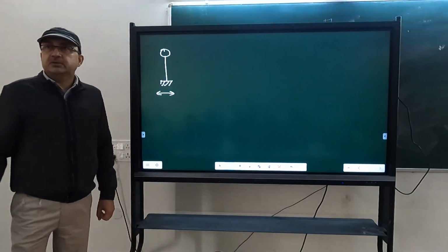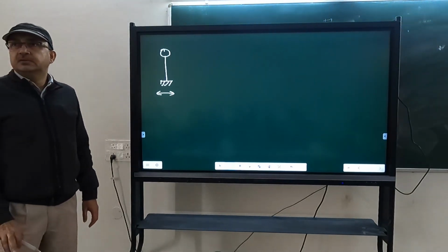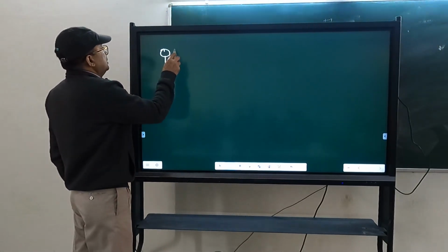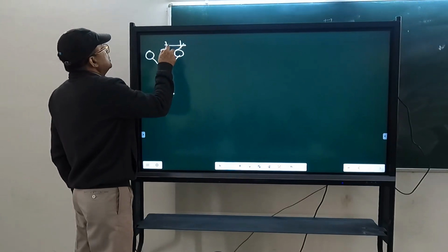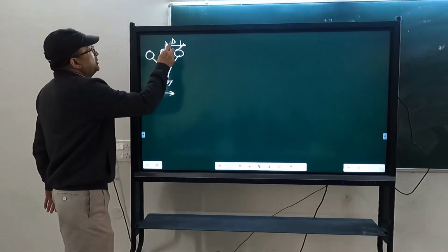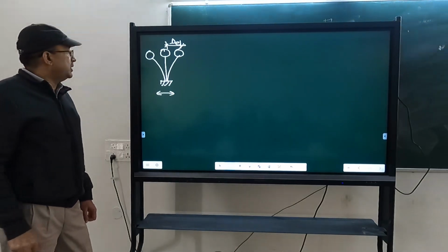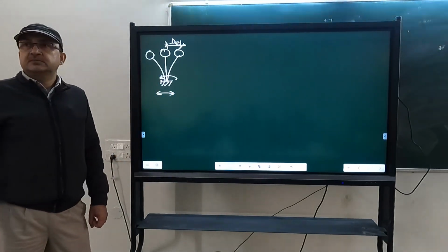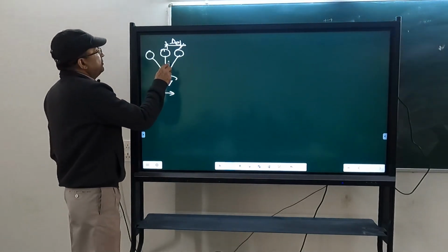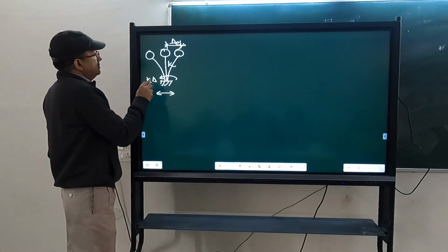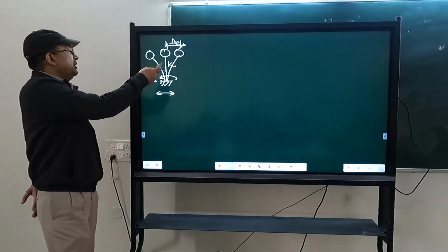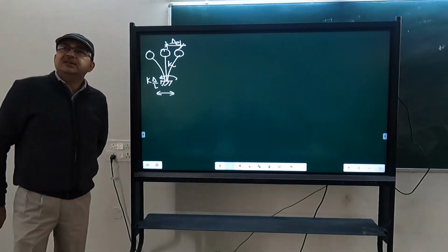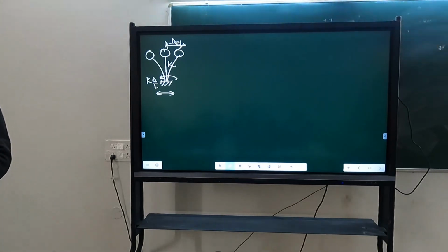It is subjected to some earthquake. It is elastic. Okay? So when it is subjected to earthquake, this elastic displacement will occur. Under earthquake, how much force will develop here? Whatever is this stiffness, K into delta. And if we are taking it angular, we can write K into delta by L. So that much moment is going to develop.